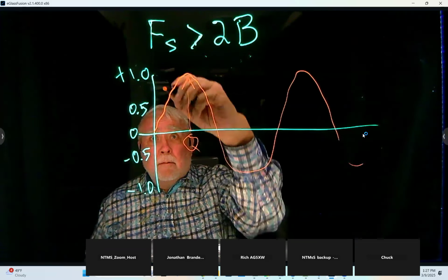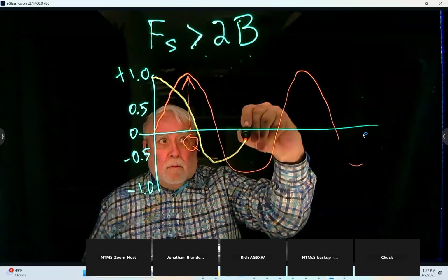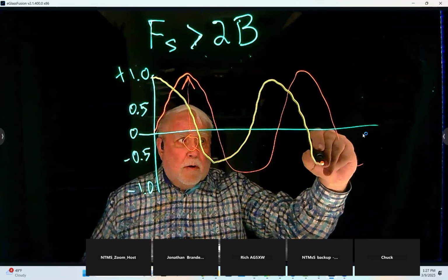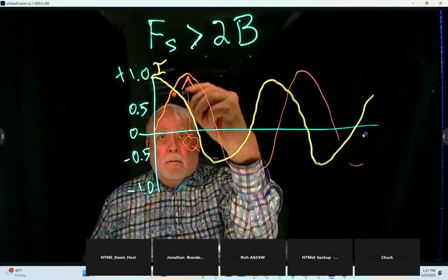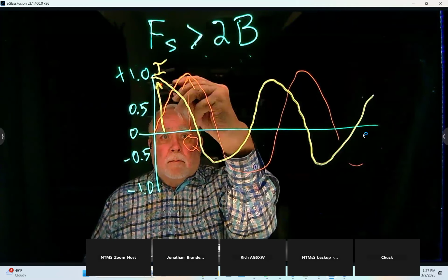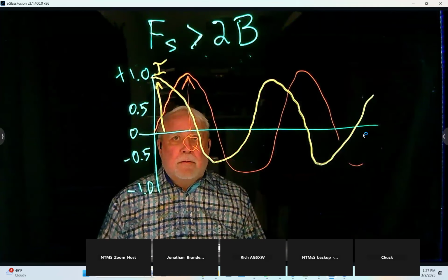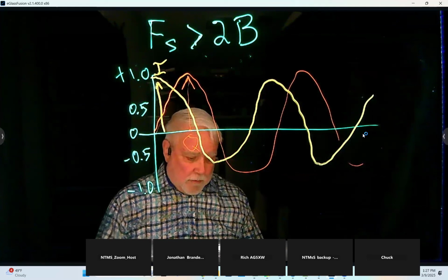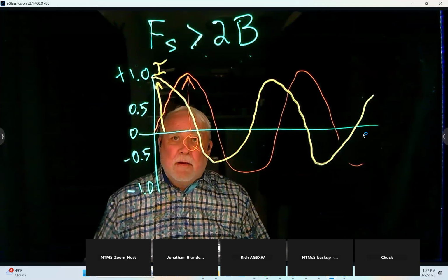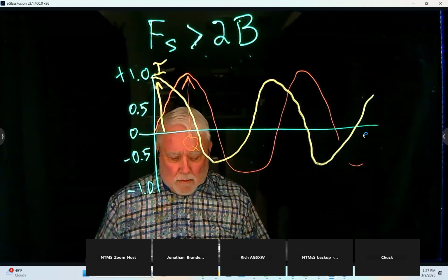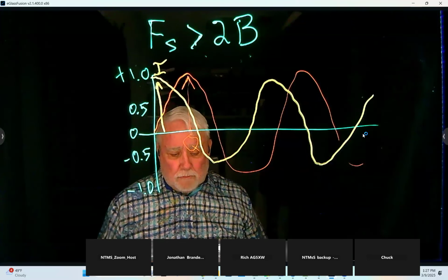And the cosine will be 90 degrees behind. And so this is the I. There. I didn't get these down to 1, which they should be, but you get the idea. We've been over this, and GNU Radio does a lot better job than I do. So we'll call the I the in phase, the Q the quadrature component that is 90 degrees out of phase, reading from my notes.